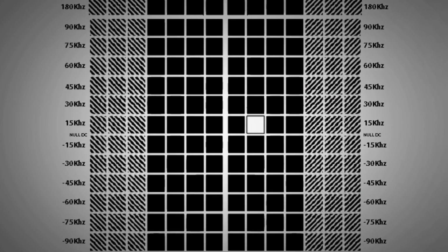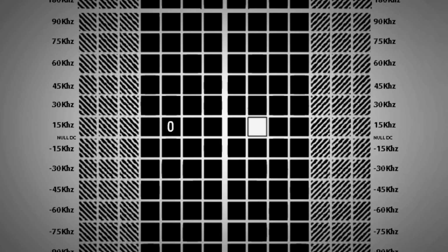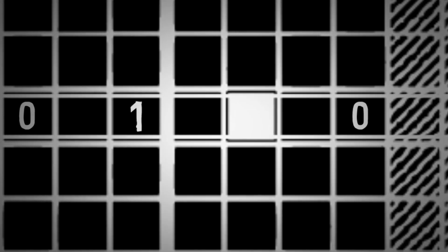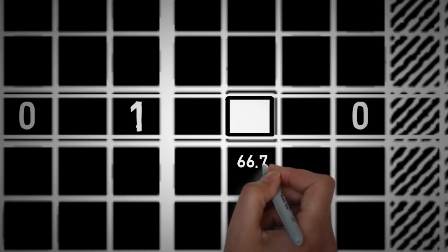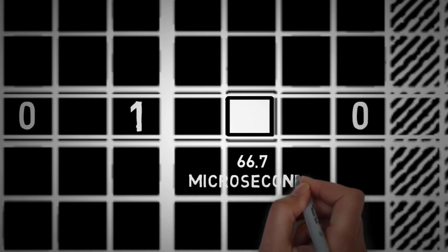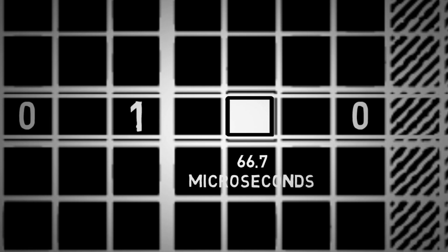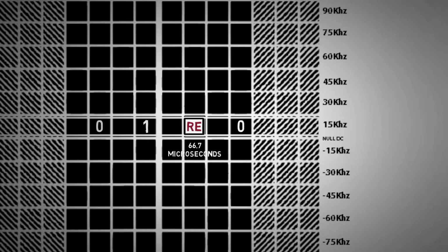Today we will discuss uplink and downlink data transmission in the network. As discussed earlier, data is transmitted in OFDMA over parallel subcarriers of 15 kHz. The subcarriers are further divided on the time axis as blocks of one symbol duration, or 66.7 microseconds. This basic unit is known as a resource element. Each resource element carries one symbol.